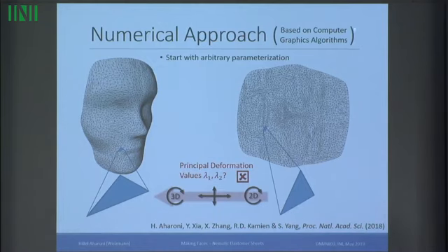But then there is an algorithm that's taken from algorithms in computer graphics for making this better, okay? It's composed of a local step of making a small linear calculation at each and every triangle, followed by solving this big linear set of equations on the positions of all the vertices.